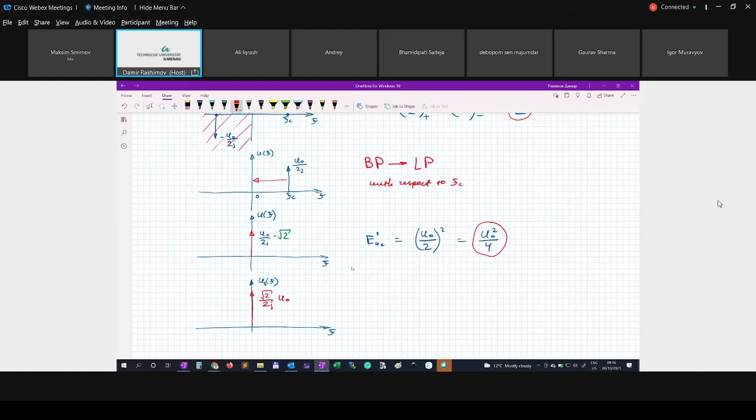So the signal in the time domain after low pass transformation, u_L2 of t, will be pure amplitude, but only for this case, because it is a delta pulse at the origin, 2j times U0. So it's an imaginary amplitude.